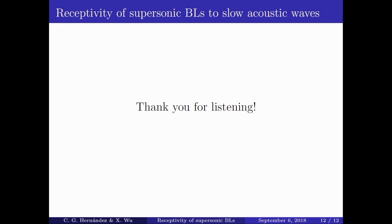So are there questions? The higher maximum is a direct resonance mechanism that Fedorov has explored. How does that relate? Well, the Fedorov theory is mainly for what's called the boundary leading edge receptivity. So in this problem, I didn't say it, but we are considering that the roughness is farther downstream.